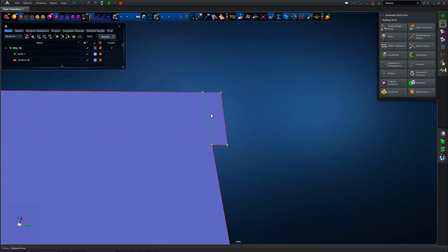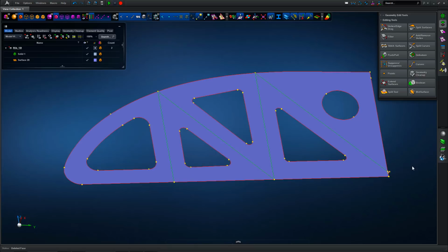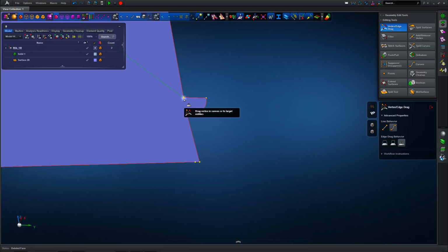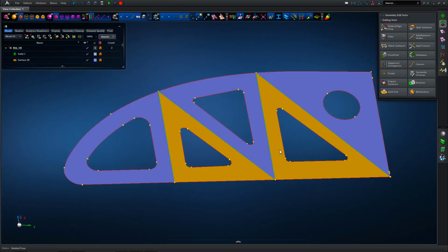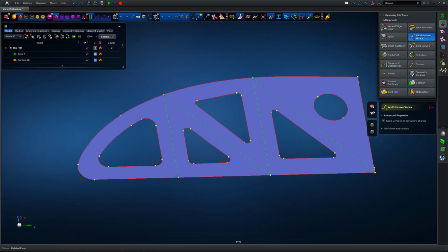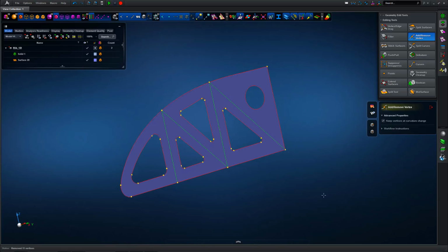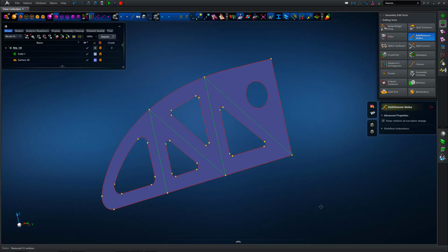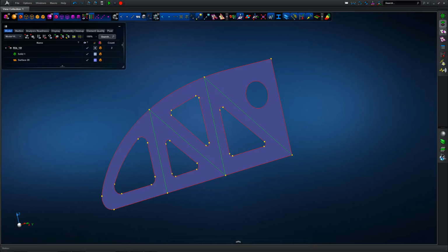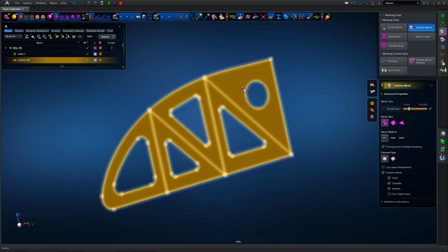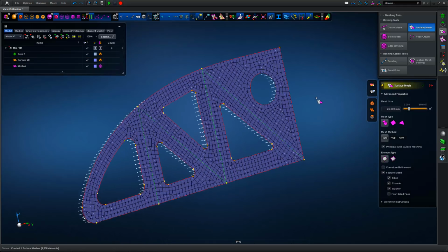All of the mesh, rather, is going to lie in the plane of the original mid-surface of the rib, as shown on screen now. So we've got the plane surface definition set up, and we have the curves in place that represent the local flange and stiffener detail, as you can see with the zigzag line across the surface there.